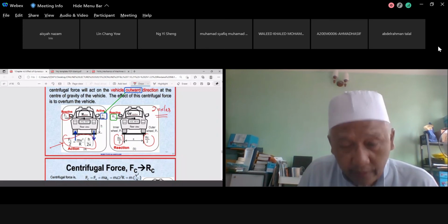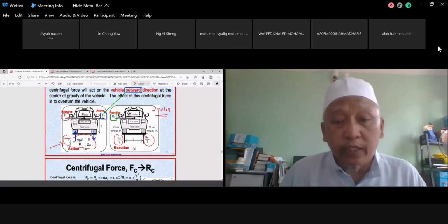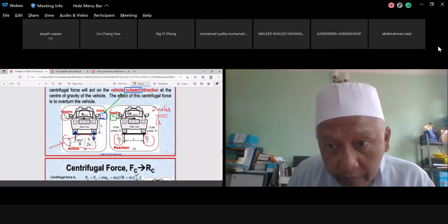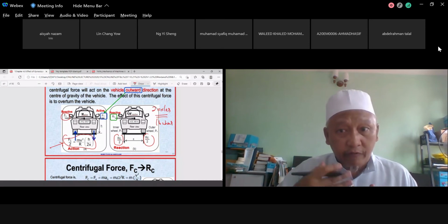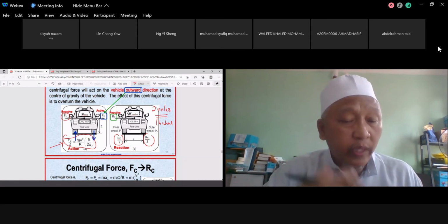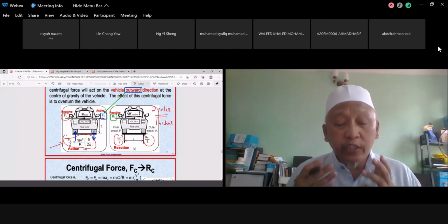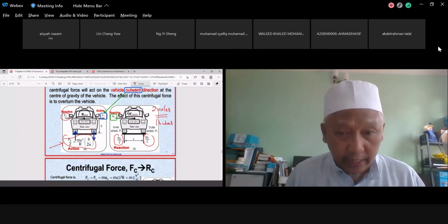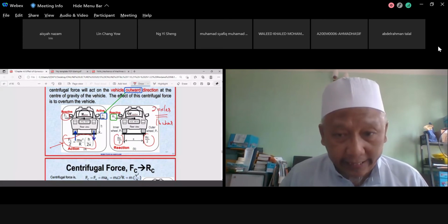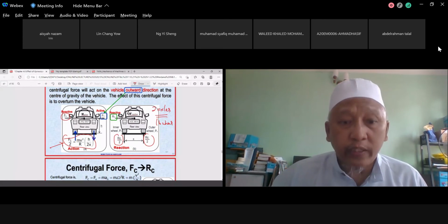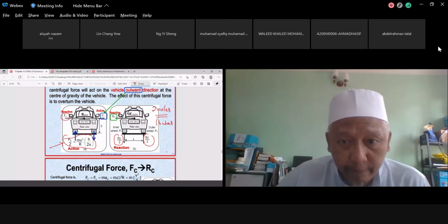Okay. So if you are talking about 16 wheels, you have to divide it by what? You have to divide it by the number of axles. One axle carries 2 wheels. And again, we are assuming what? We are assuming the same axle carries the same weight, because the CG falls at the center. But if you design the actual thing, it is not so. This one is for the simplification of our calculation.